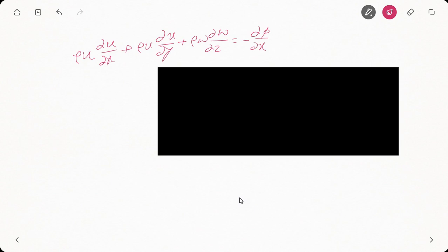Now we have to non-dimensionalize this, so we first write rho by rho infinity. So we write one rho infinity here, and then u by v infinity, so one v infinity is here, and then we have again one u inside. So you write u by v infinity. So we get v infinity square, divided by dou x by L, where x becomes L. This is our first term.